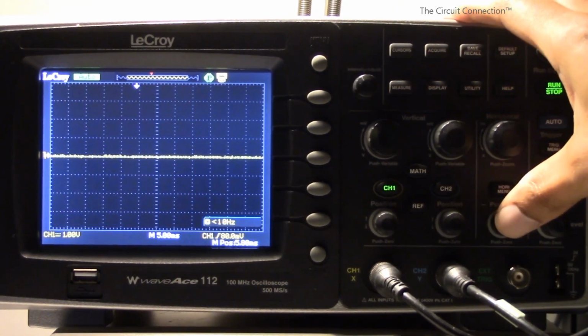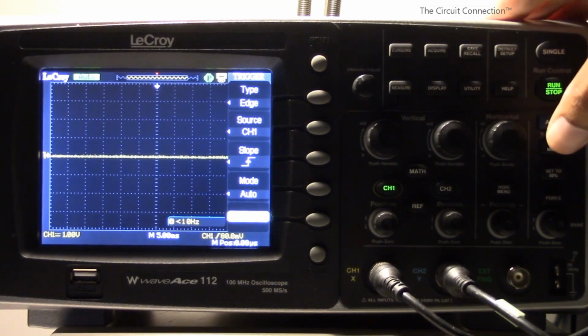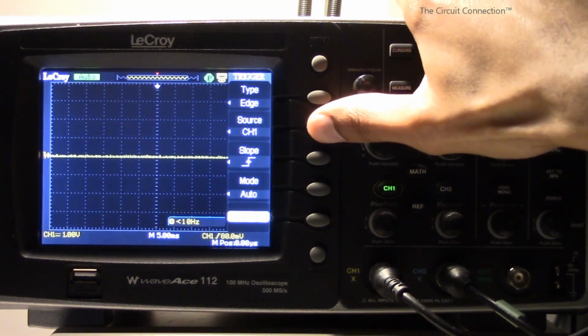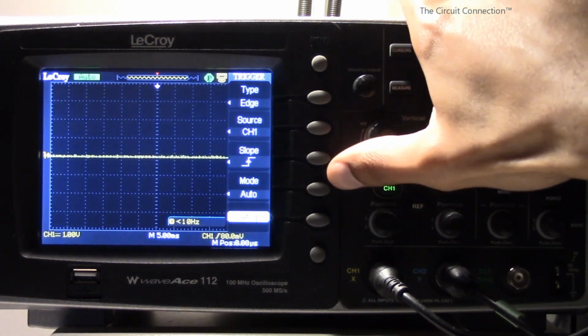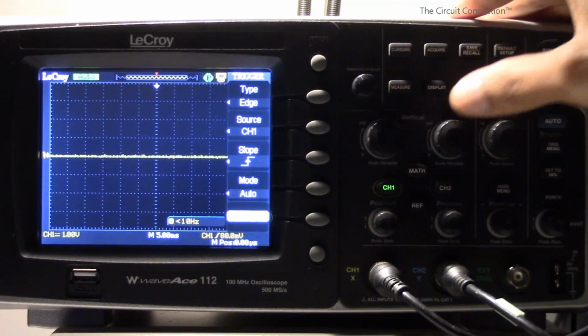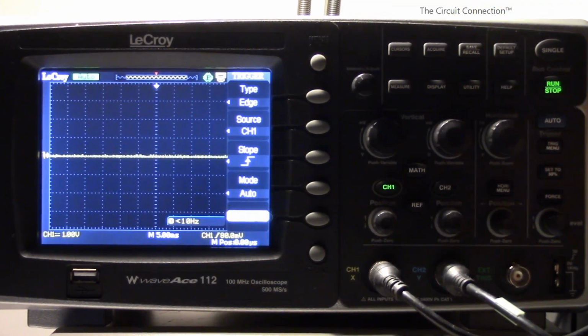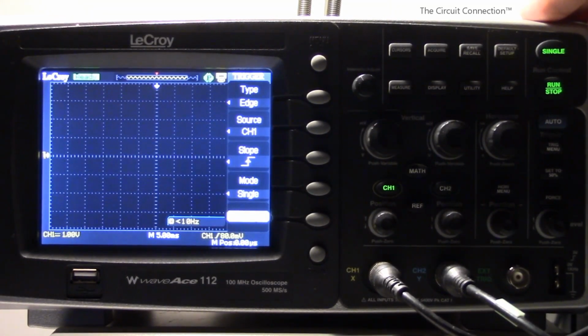On this oscilloscope, just press the button and it'll put you back to your default value of 0 for that. Okay, so that's my time span set up there. Now let's go on to the trigger. In my trigger menu here, I'm going to use edge, and I want my source to be channel 1. I'm not going to use channel 2 for anything. For my slope, I'm going to be looking for a positive slope, because remember, it's going to be charging up. And right now it's in auto, but I'm going to set that up for single.